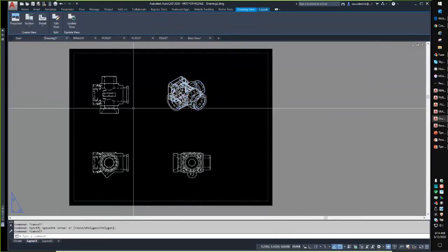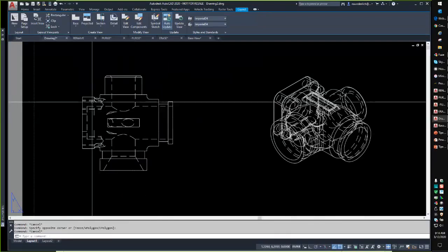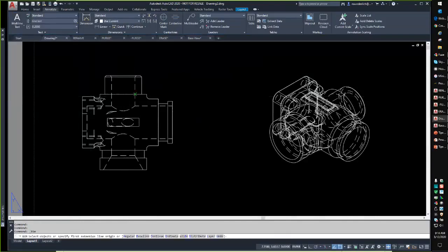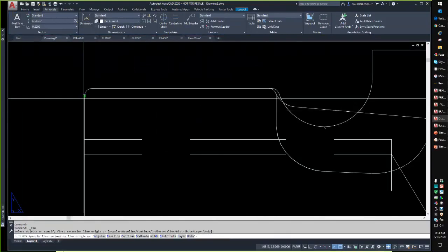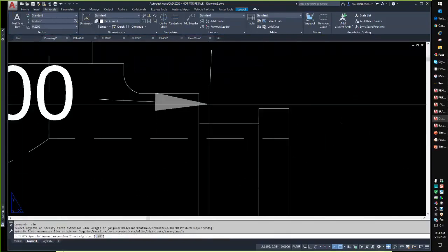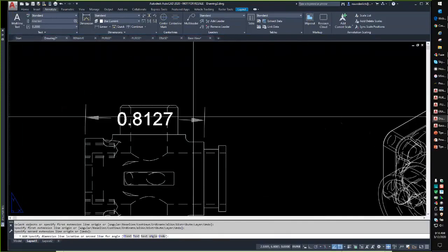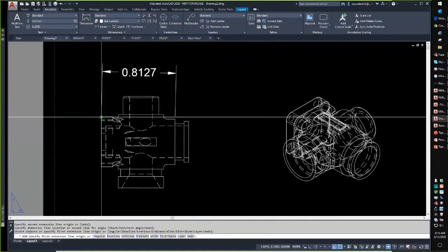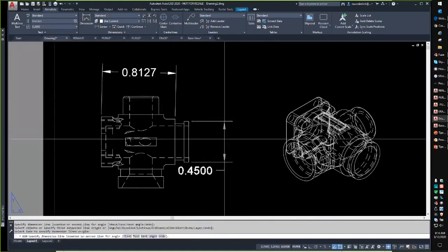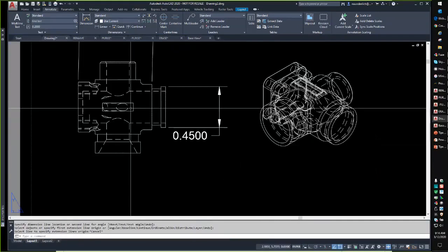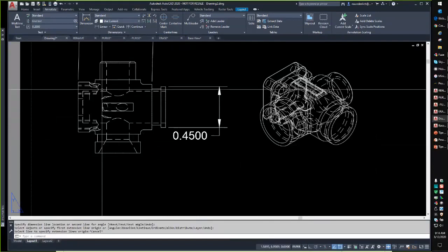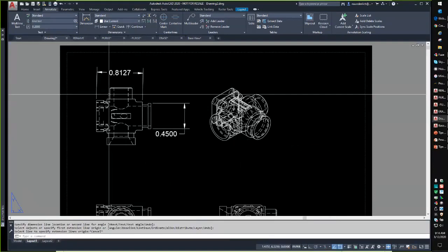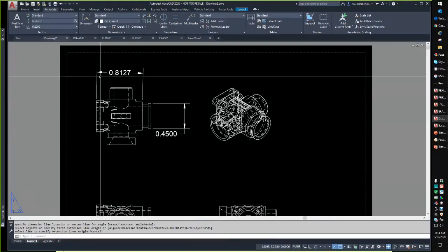So you have this, and the nice thing about this is if you have the Inventor part, you can use what's called transspatial dimensioning. So I can go to my annotate and run a standard dimension through my transspatial dimensioning. I can pick this endpoint, and this endpoint here. That's a rotated dimension, but that would be the actual dimension between this point and this point. That's 4.5. Again, I don't need to know exactly what size the part truly is. With transspatial dimensioning, if I'm dimensioning in the viewport or the base view from model space and I'm using my O-snaps, it will give me the correct dimensions.